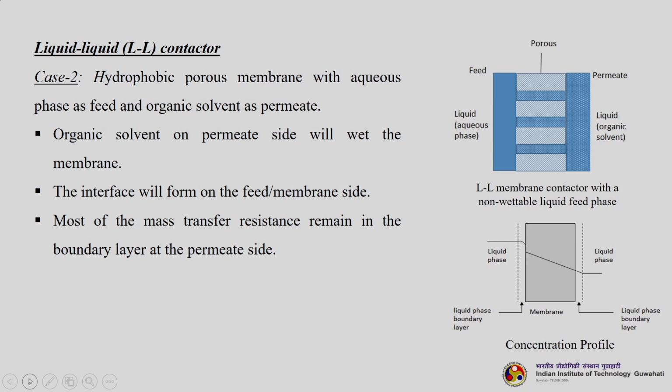Then case 2: a hydrophobic porous membrane with aqueous phase as the feed and organic solvent as the permeate. Here you can see the feed phase is an aqueous liquid, but on the permeate side it is an organic solvent instead of an aqueous solvent. The organic solvent on the permeate side will wet the membrane. So, you can see now the pores are filled from the permeate side liquid, and the interface will form on the feed and membrane side.